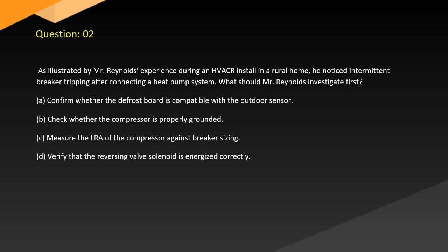Question 2. As illustrated by Mr. Reynolds' experience during an HVACR install in a rural home, he noticed intermittent breaker tripping after connecting a heat pump system. What should Mr. Reynolds investigate first? A. Confirm whether the defrost board is compatible with the outdoor sensor. B. Check whether the compressor is properly grounded. C. Measure the RLA of the compressor against breaker sizing. D. Verify that the reversing valve solenoid is energized correctly.